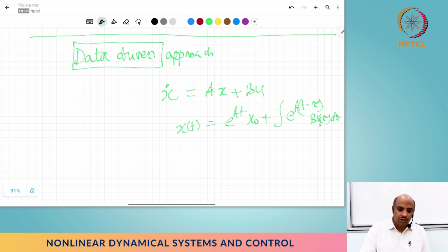But that u, in continuous time, depends on certain data available directly in raw form, so why not use it? Essentially, you express u directly in terms of x1, x2, x3, where these are all in the discrete time sense, the values at particular times. So you collect the data over a particular time. As I said, this is typically implemented in discrete systems and works out very well for discrete systems. You collect the data over a certain number of periods, put them in a certain format, do some magic with it, and then get the result, right?